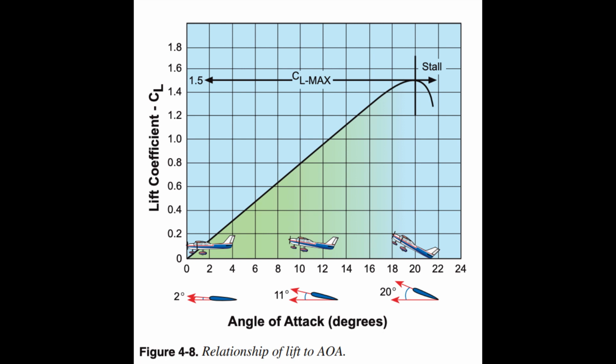This pressure requires energy that is taken from aircraft performance, speed. Therefore, when the CG is closer to the aft portion of the aircraft, the elevator downward forces are less. This results in less energy used for downward forces, in turn resulting in more energy applied to aircraft performance. Thrust is controlled by using the throttle to establish or maintain desired airspeeds.